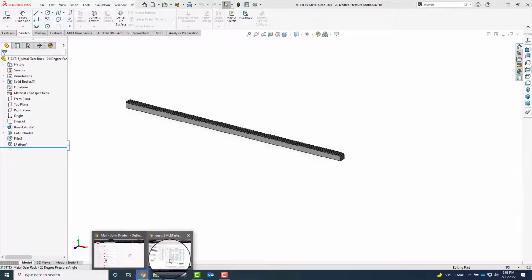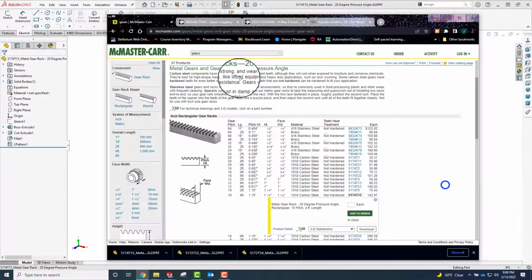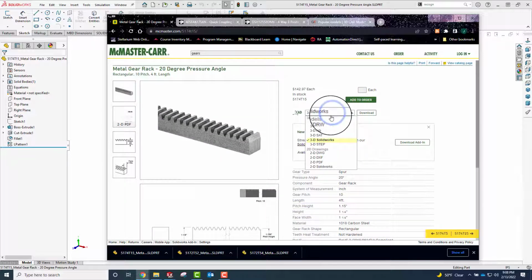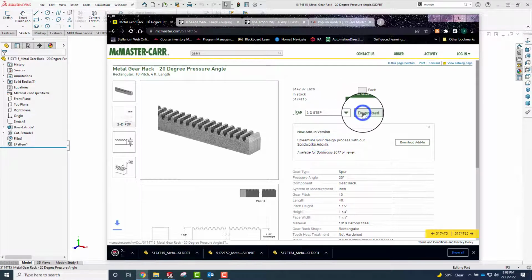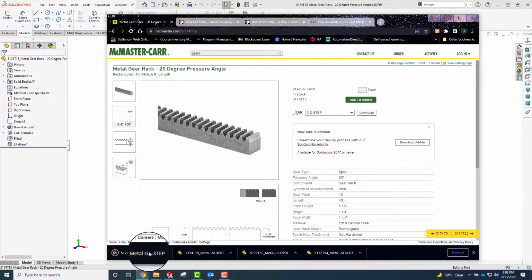if we go back and look at this same part in detail. If instead of getting a SolidWorks file, I downloaded, let's say, a STEP file. That's another really common kind of interchangeable 3D format, so it's not SolidWorks specific. When I download it, you can see SolidWorks recognizes it. It puts the icon type as being SolidWorks, but the tail end of the name there is .stp instead of .sldprt. So let's go ahead and open that.